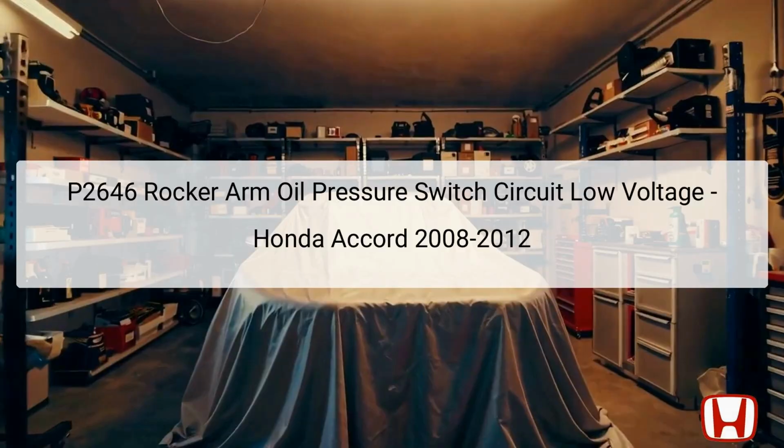In this presentation, we will address the DTC P2646, which indicates a low voltage condition in the rocker arm oil pressure switch circuit for Honda Accord models from 2008 to 2012. This diagnostic trouble code, DTC, relates to issues affecting the VTEC system, which is crucial for optimizing engine performance by controlling the timing of the intake valves.